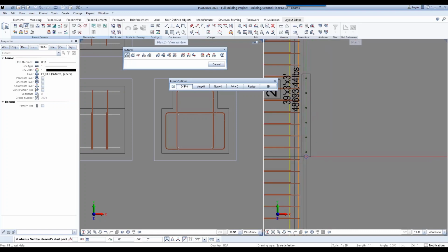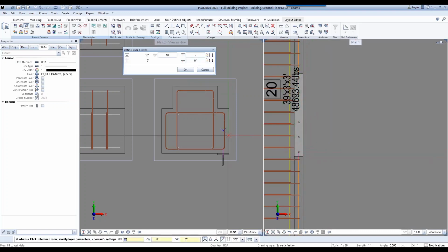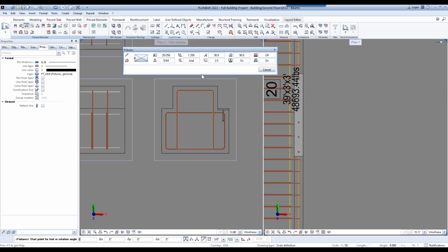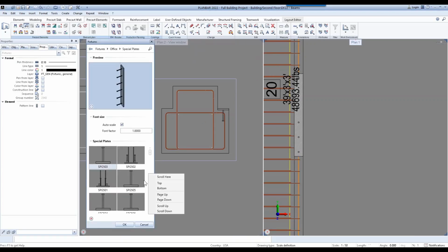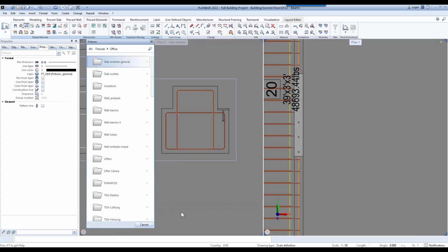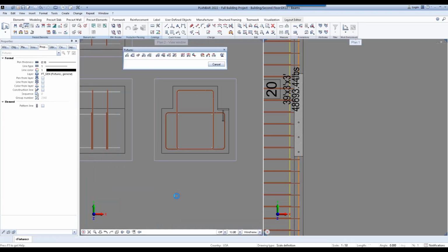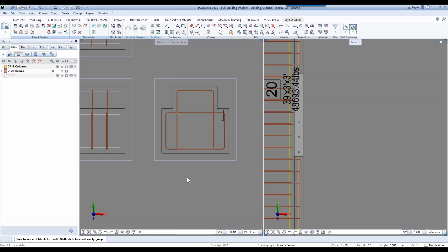And then we're going to place the plate here. See, it pops up at the bottom of my beam. So if I want it to go all the way to the top, change the elevation and click cancel. We don't need to label it. And then it's prompted me to place another one. We don't need to. We can exit out of that.